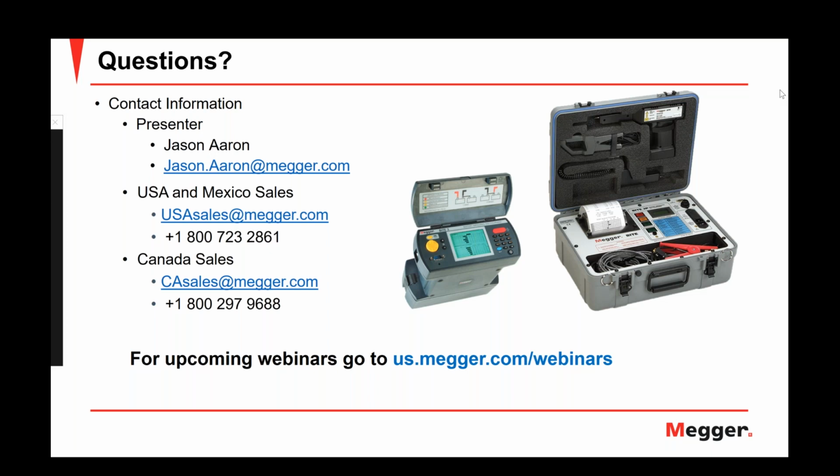Once you've done that, you're going to follow the similar procedures that we talked about for the BITE 3. You're going to make sure that the receiver's powered up and that you have everything connected, and then you're going to start that process where you select the COM port that you have it plugged into, and then follow the prompts as we talked about. Once you have all of that configured and set up, you'll be able to finish that process, and the information that you have stored in the receiver will be able to export to PowerDB.